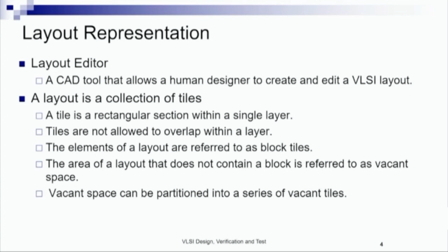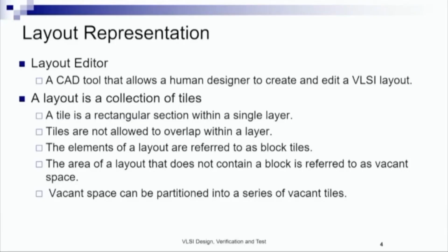The blocks in the circuit will be represented as block tiles. The vacant spaces will be represented as vacant tiles. The area of the layout that does not contain a block is referred to as the vacant space. The vacant space can be partitioned into a series of vacant tiles.